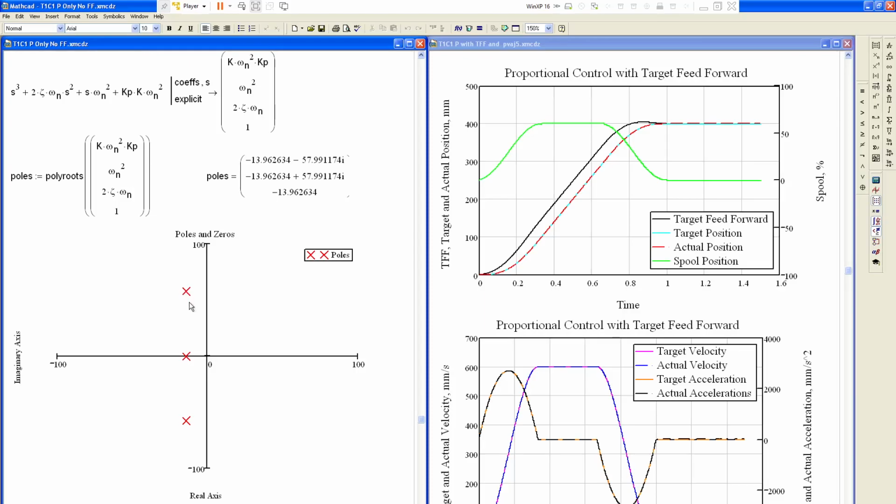And the problem with this closed loop transfer function is that if I want to move this pole closer, these poles move away. Or if I move this one this way, these 2 poles will move here. And that's definitely not desirable, because then what happens is you can see oscillations. But if I move this real pole closer, it slows down the response. So this is really about the optimal placement for the 3 poles. But I only have 1 gain, so I can't place these 2 extra poles at the same location.